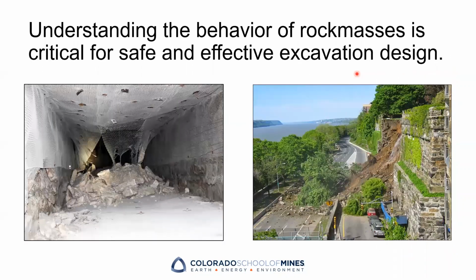My specific BBM was used to look at stress-strain behavior of numerically modeled rock samples as a potential rock mass analog. One important purpose of studying rock mass behavior is to be able to create safer and more effective excavation design. Understanding how rock masses behave before and after failure is critical for both tunneling applications, in this picture here, as well as surface excavations, like the one here, which was done for a roadway. Engineers want to avoid catastrophic failures, so there is great importance in understanding the stress-strain behavior of the rock mass in which the excavation will take place.